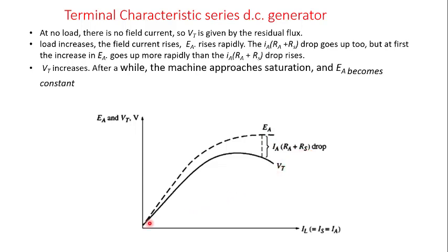When you bring the two things together, the terminal voltage is going to increase, then get to a particular point that we call the saturation point, where the voltage is going to remain constant. No matter the load, either you increase the load or whatever, the voltage is going to be constant. We call it saturated. We will talk about that as we move on in this course.